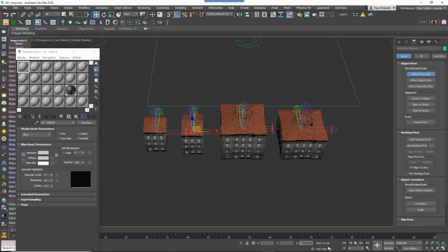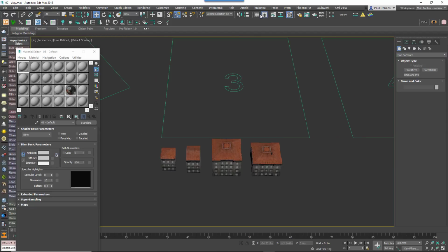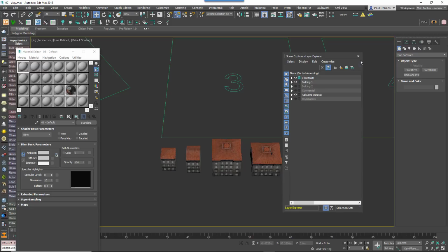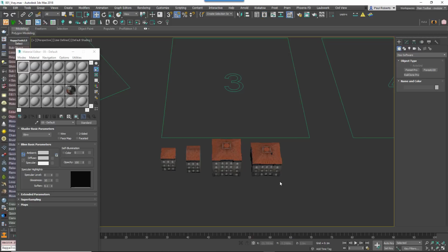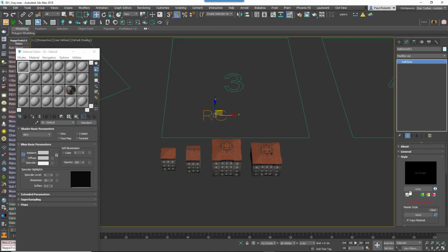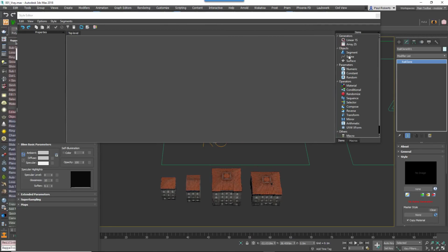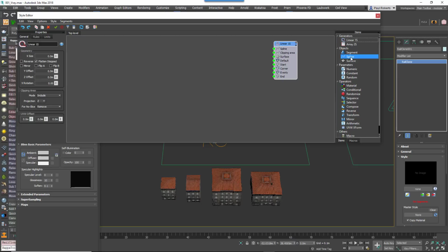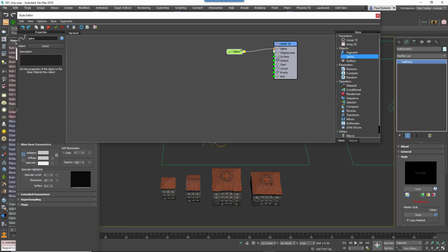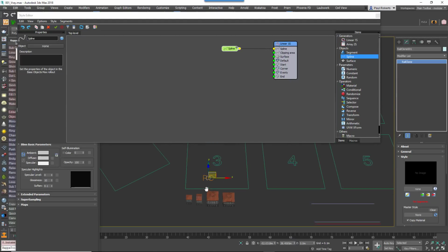This one will add buildings around the perimeter of a city block and is particularly suited for courtyard, townhouse and terrace style architecture. So create a new RailClone object and open the style editor. Create an L1S generator and wire a new spline node to the generator's spline input. Use the spline node to select the test spline we created in step 2.